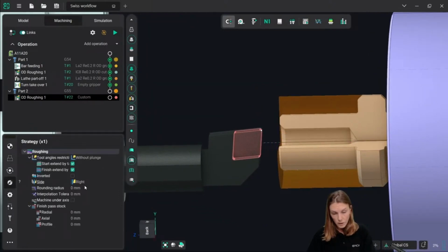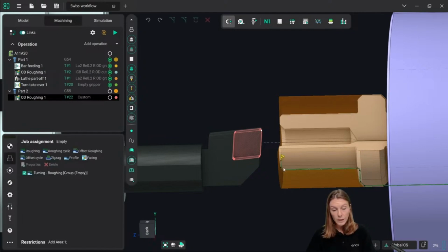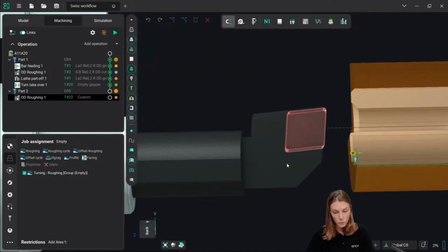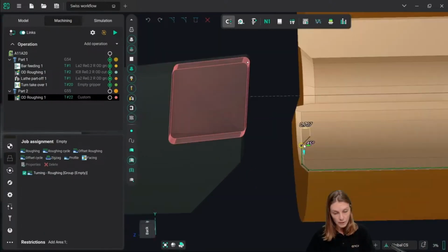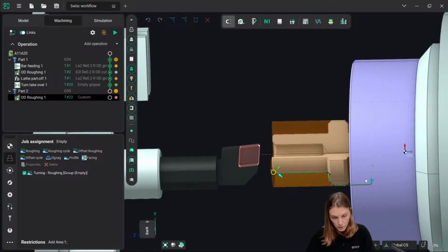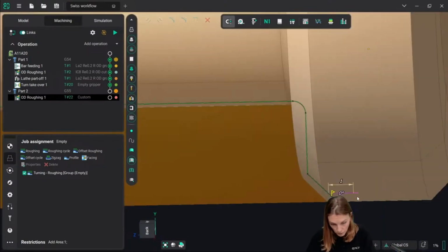For this, we need to change the machine on the axis. So we will program the machining in the negative area. Swiss type places the machine in negative X area. And we're going to do the same. We're going to cut a little bit of the profile and make it a little bit simpler. So lead ins and lead outs.